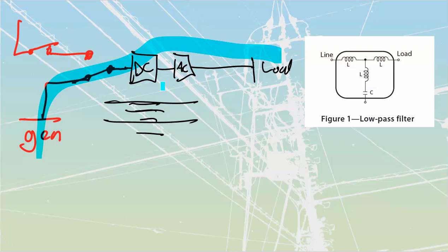Talking about line reactors, they're the simplest and the lowest cost means of attenuating harmonics. It's simply going to be a coil that's going to be in line with my lines. We connect them in series with individual nonlinear loads. They're low cost, and they are going to give us smoothing, because that inductor is what we refer to as a choke. They are going to use that magnetic field to deliver current anytime that our supply is failing on that end.